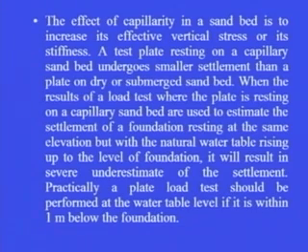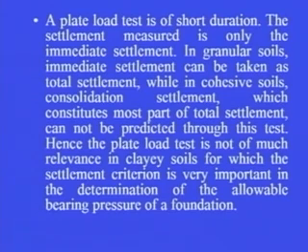Practically, a plate load test should be performed at the water table level if it is within 1 meter below the foundation. A plate load test is of short duration. The settlement measured is only the immediate settlement.